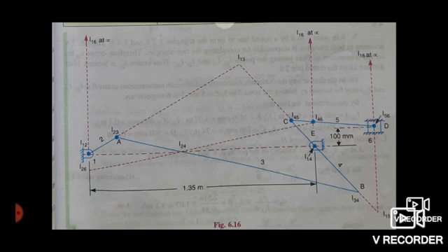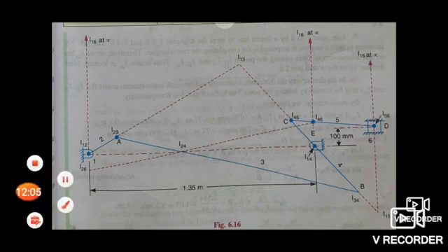I34 is the right bottom point B, and I14 is point E. So if we join the instantaneous centers I34 and I14 and extend this, it meets the I12 and I23 line at point I13. There the center I13 is located, and mark number 10 on the dotted line 1 3.